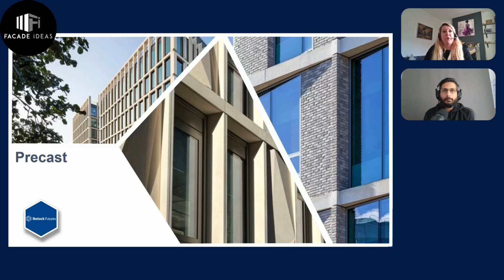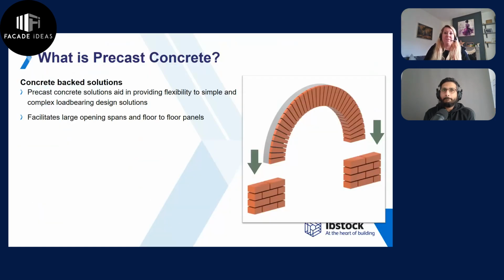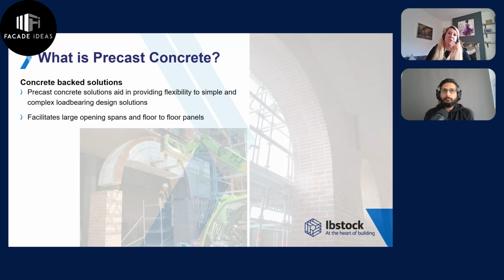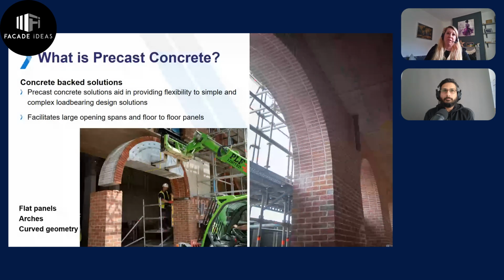Moving on to precast units, we can use these in both soffit and elevational treatments. It's a fairly simple solution that has been around for a long time, but it offers great flexibility. Here we have a precast arch with a brick-faced soffit finish. Typically, precast is a load-bearing element, as you can see from the little diagram. Putting that into real terms, you can see the soffit units we supplied for this project in Liverpool.